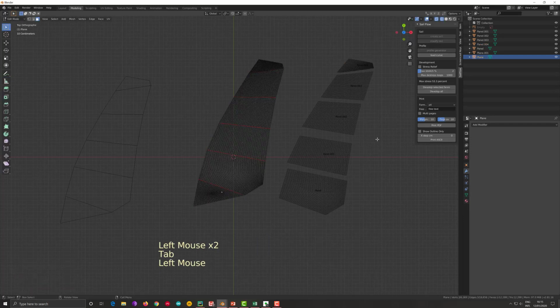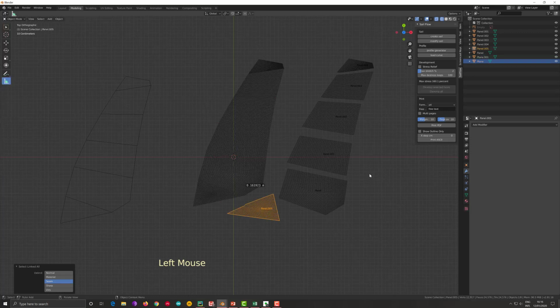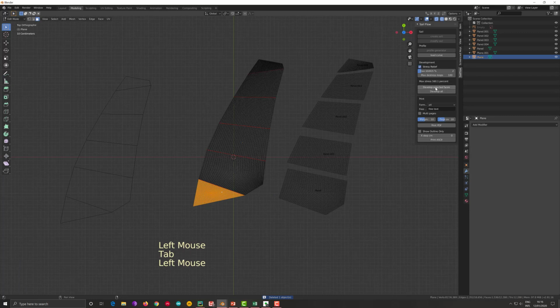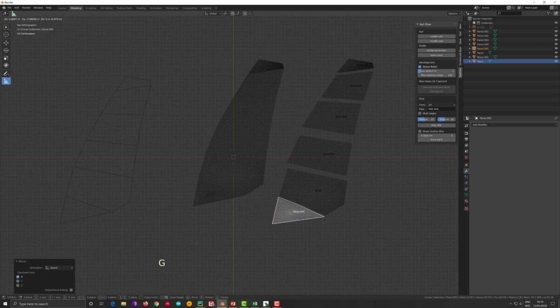And here the last part of the sail. Again, Control L. This time, maybe I will need later on to distress this cloth a bit. Let's try. Okay, I have 140% of stress, so I enable the stress relief this time. The algorithm takes a while, and okay, here I have it, and here's my panel. 15% is a small panel, so it seems to be okay. Okay, I have all the panels, and I can go and print them.